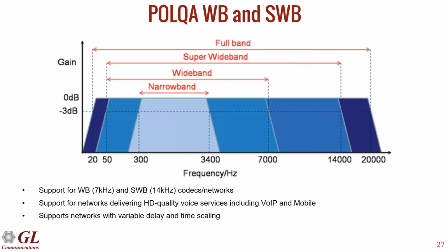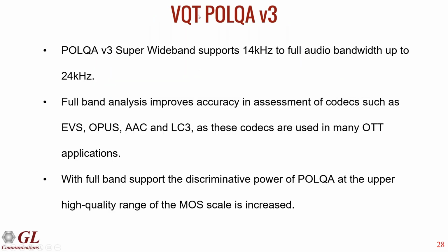Now, POLQA supports narrowband, wideband, and super wideband audio. This is the full band of an audio spectrum. The reason I mention that is because we now support POLQA version 3, which is the latest POLQA version, and this supports full bandwidth, up to 24 kilohertz. So this fully supports full bandwidth.